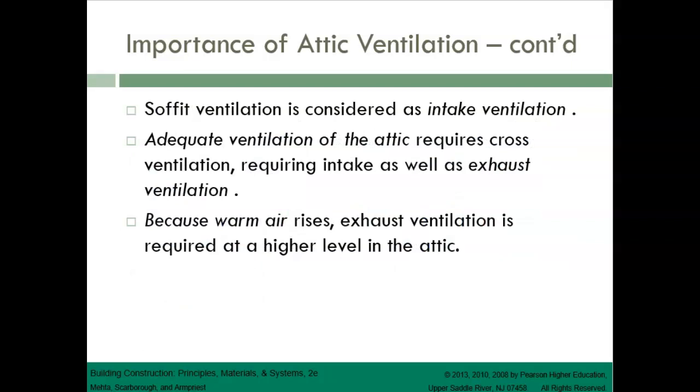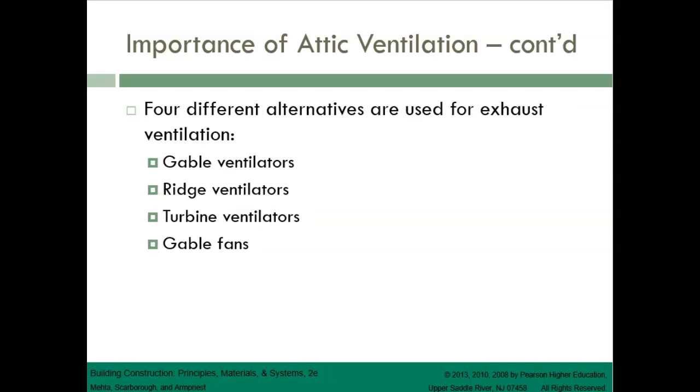Soffit ventilation is considered as intake ventilation. Adequate ventilation of the attic requires cross ventilation, requiring intake as well as exhaust ventilation. Because warm air rises, exhaust ventilation is required at a higher level in the attic. There are 4 different alternatives used for exhaust ventilation: gable ventilators, ridge ventilators, and turbine ventilators. Gable fans can also be used.